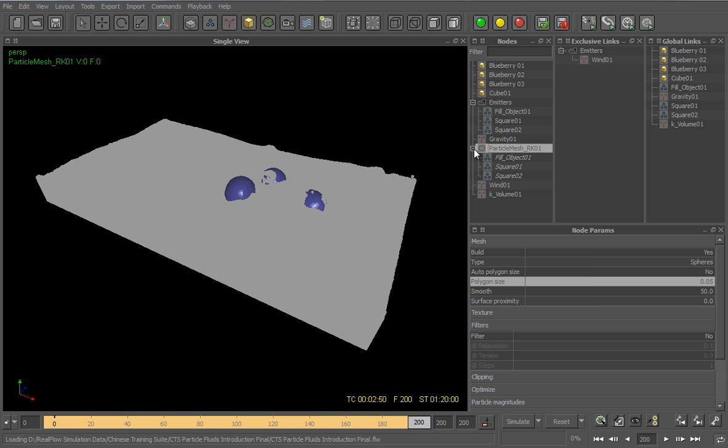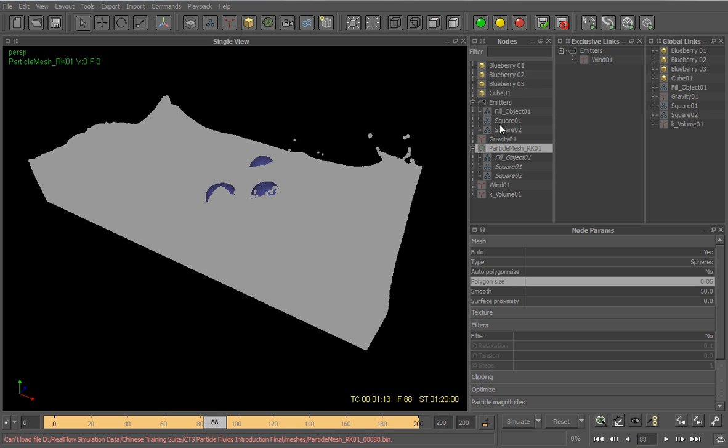A mesh engine creates spheres with a certain radius around the particles and blends them together. The number of polygons determines the resolution of these spheres and finally the level of detail. Therefore, the mesh parameters are subdivided into 2 areas. In the first section, we can define the polygons and the look of the mesh.